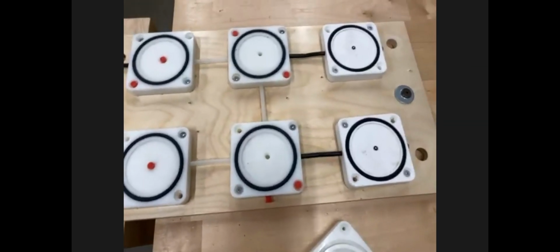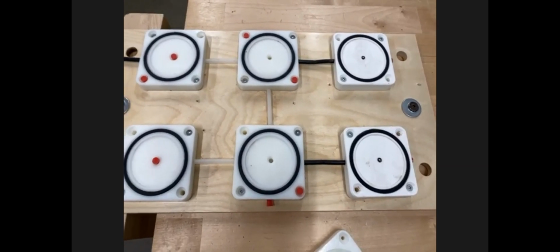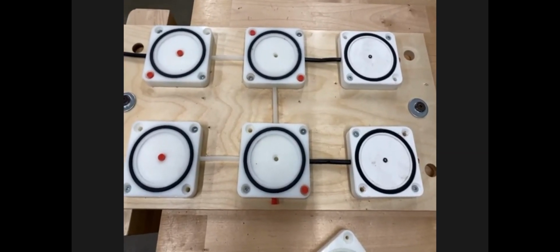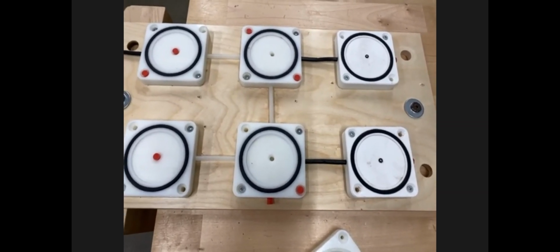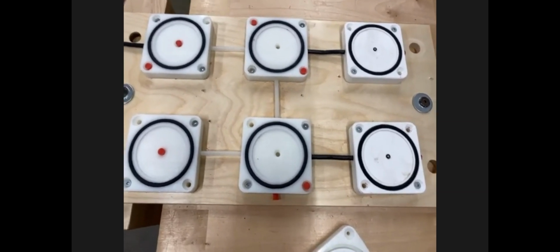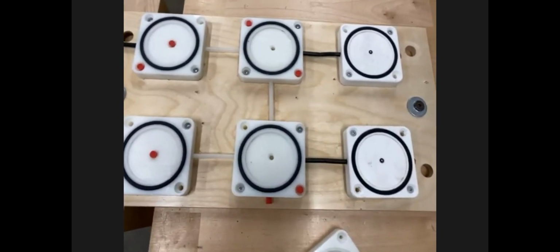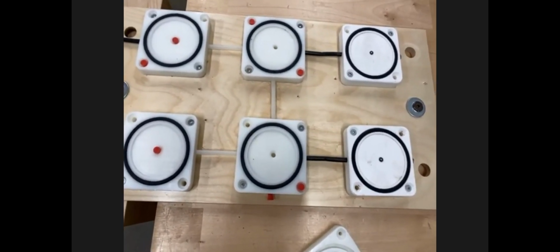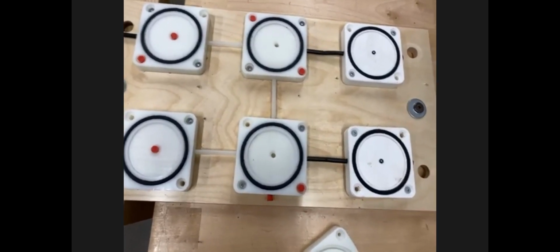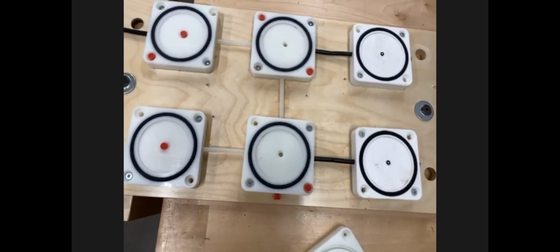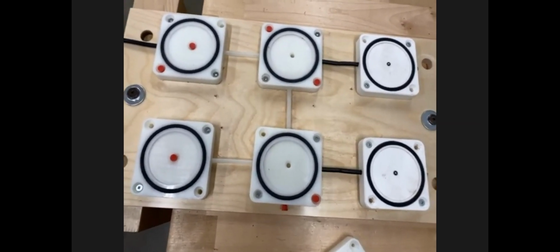So just one more thing. If you had, for example, on this board, 6 pucks, would the difference in vacuum pull be significant when you have all 6 open as opposed to closing down 4 of them or whatever? You're going to get much better vacuum holding power when you have 6. It's directly related to the amount of surface area that you have. It's directly proportional to that. It's pounds per square foot. So the bigger the surface area, the more holding power you're going to have.